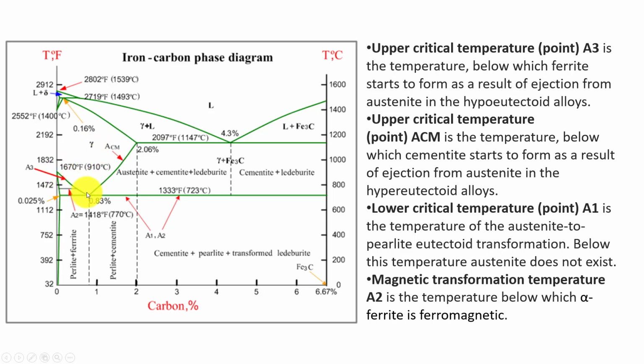And if we go above that line, we're going to austenite. That's going to erase all effects of any other heat treatments, things like that. We're going to see grain regrowth. Remember our grains being regrown, we talked about that in recrystallization. So upper critical, definitely above these temperatures here.